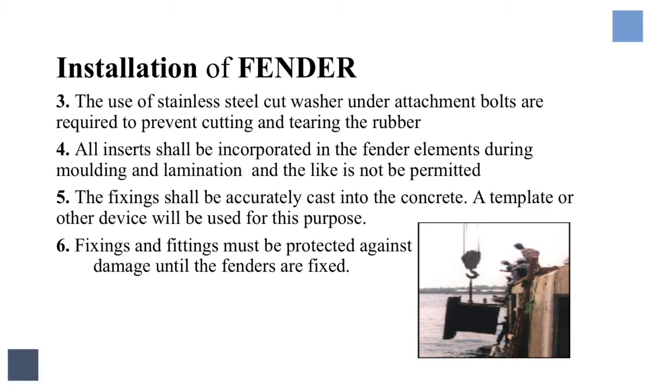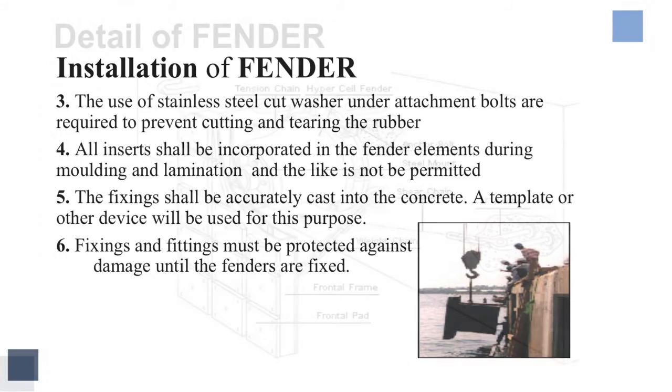Third, the use of stainless steel cut washers under attachment bolts is required to prevent cutting and tearing the rubber. Fourth, all inserts shall be incorporated in the fender elements during molding and lamination, and the like is not permitted. Fifth, the fixings shall be accurately cast into the concrete. A template or other device will be used for this purpose. Sixth, fixings and fittings must be protected against damage until the fenders are fixed.